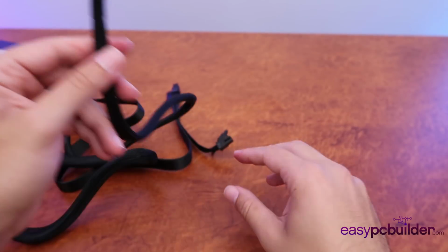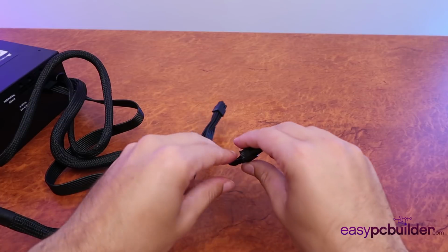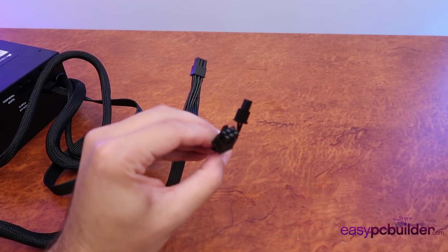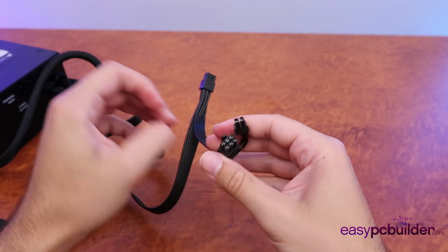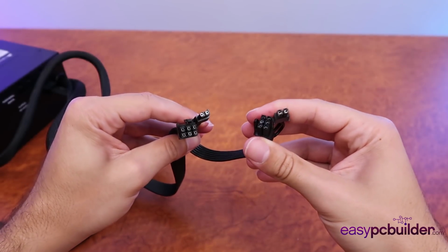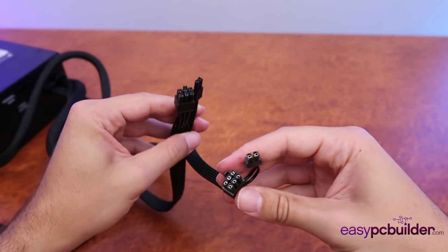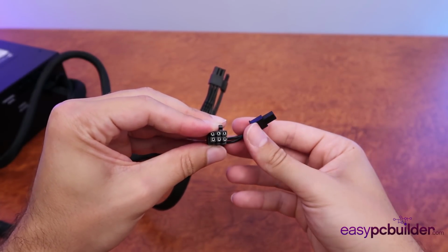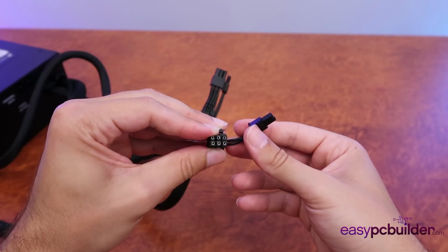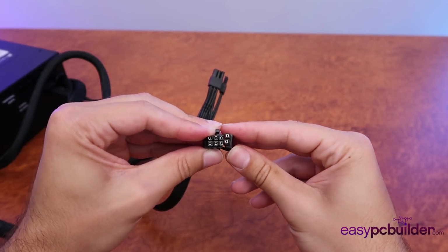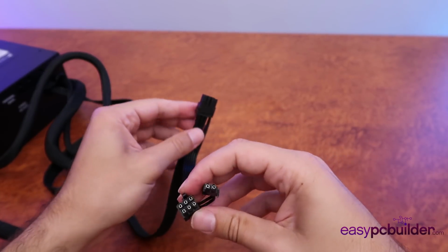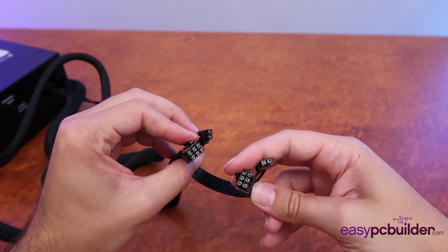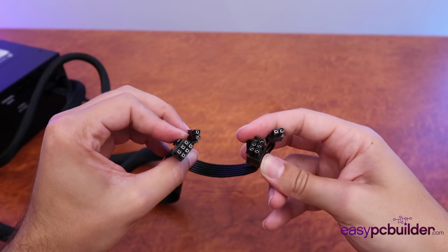And the third here for any high-end graphics card as well is either a 6 or 8-pin power connector, of which there is usually 2 off of any modern power supply. Graphics cards will either accept 6 or 8 pins. 6-pin is a 75 watt power to the graphics card and 8 pins is 150 watts. Generally, you'll either run the two of these in either 6 or 8-pin or a combination of both. We talk more about power supply mounting and the cables in our build video.